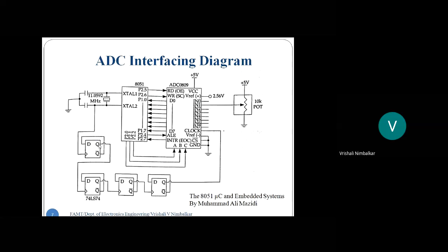Fine. And see the diagram here, D flip-flop has been shown and the signal is going to act as a clock. Now D flip-flop, see the connection, Q bar is connected to D. What are these? These are the toggle flip-flops. With every clock pulse, this is going to toggle. And the connection is, crystal oscillator is connected to the first toggle flip-flop. Output of first is a clock to the second. Output of second, clock to the third. And output of third, clock to the fourth. And the fourth flip-flop acts as a clock.